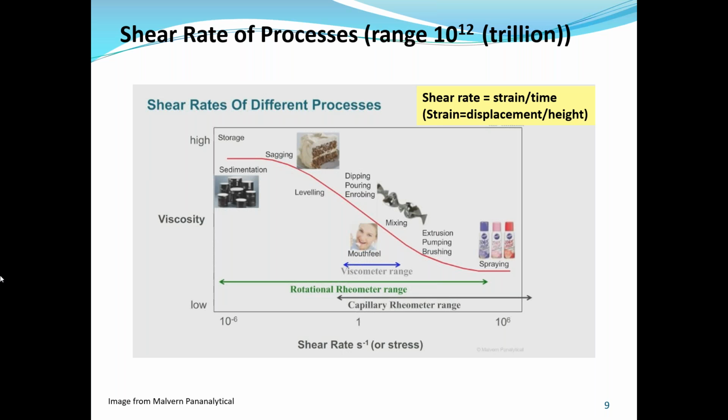All right. So certainly with a rheometer, you could easily set the temperature at 5 degrees. That's a standard assay temperature, and it is pretty solid. In terms of gap height and positioning, it depends on if you're looking at viscoelastic properties, an oscillation type measurement. I would think somewhere between 0.2 to 1 millimeter would be reasonable.